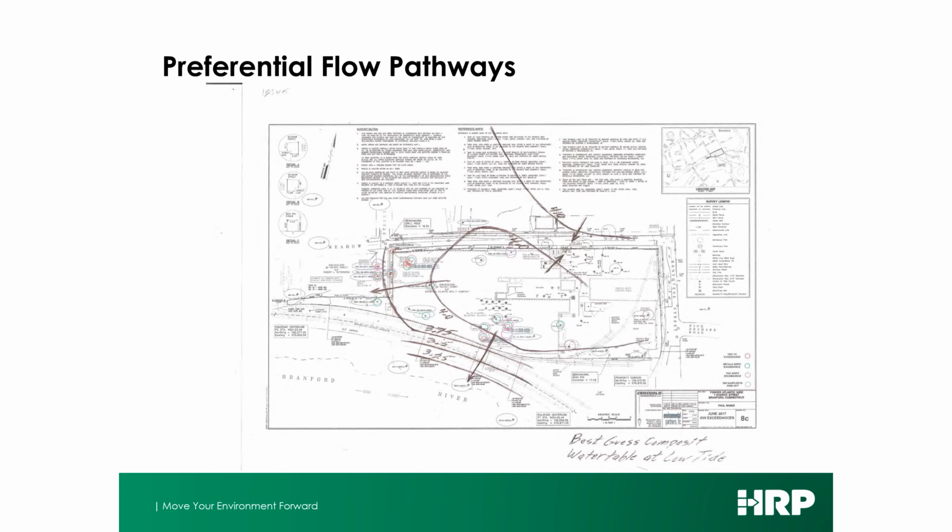At the western extreme of the developed portion of the site, and then at the southeastern, where I kind of had groundwater going originally back 20 some odd years ago, there are drainage pipes going under the tracks with porous backfill and then into the river. And what I'm seeing, and what the groundwater contours and the contaminant transport is telling me, is that it's going not directly at the river, but it's finding its way around the edges.